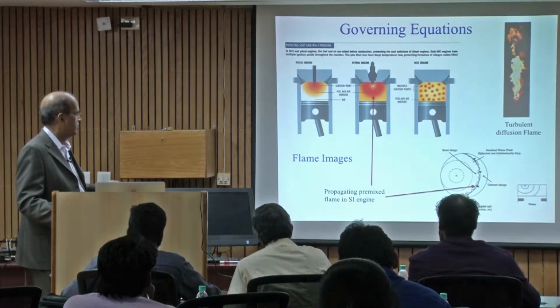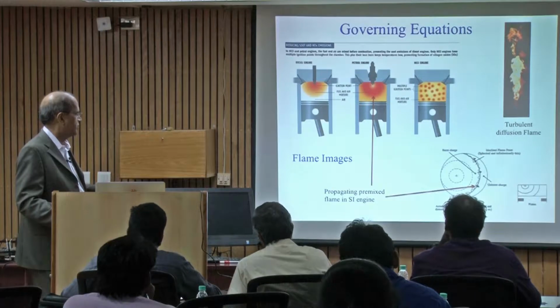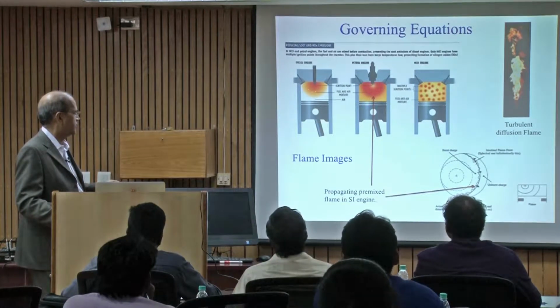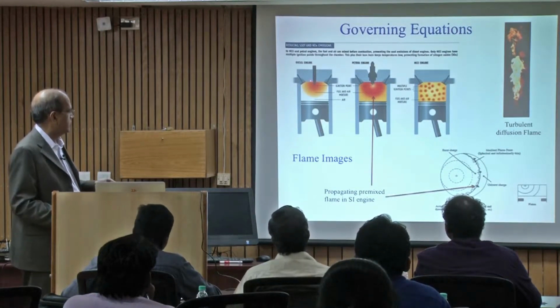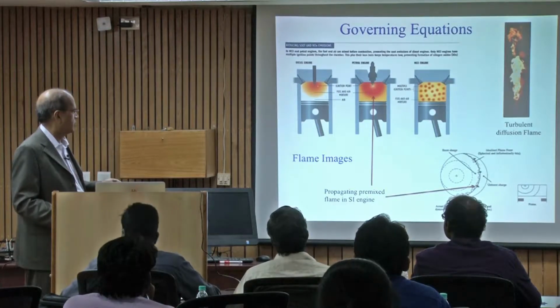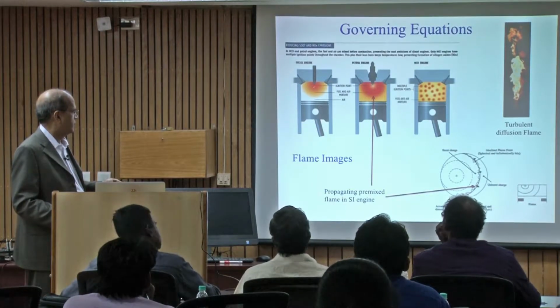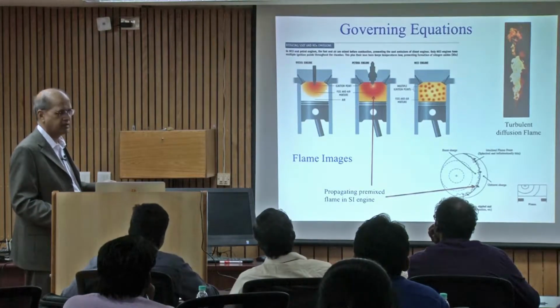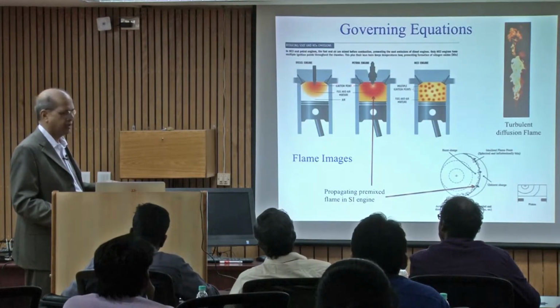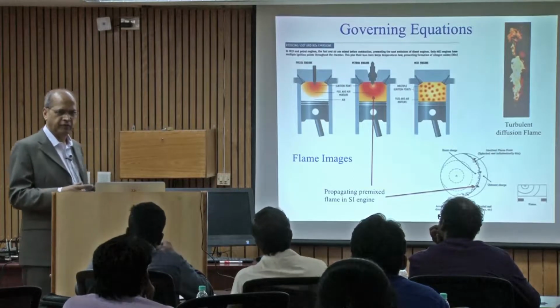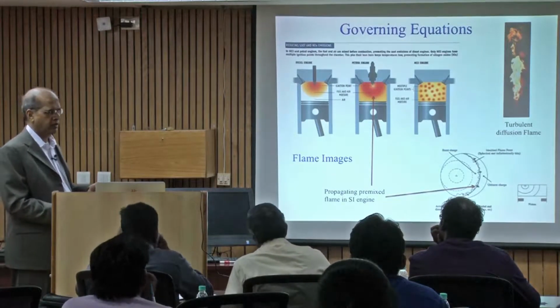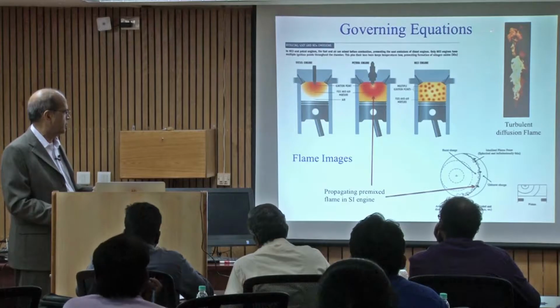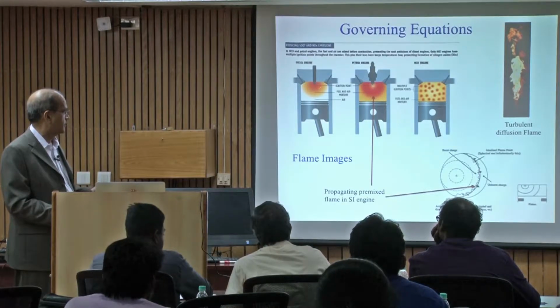So without going into a lot of details about crank angle and injection time, just overall, you inject the fuel, and then the fuel will atomize, break into droplets. Okay, and then the fuel vapor will mix with air. Okay, and it will start ignition and then combustion process.